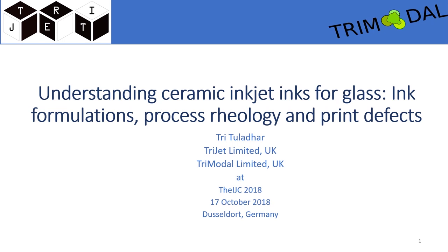that. That's a part, but I'm looking at ceramic inks printing on glass, which has ceramic inks plus a glass frit, so it's a two-particle system, which is much more complex than your tile. And more important, we're printing on glass, right? So there are so many defects you don't see printing on tiles. They come when you're printing on a hard substrate. Like the former speaker talked about printing on the edges and all that, the line definition becomes quite a critical issue, which you don't see when you're printing on a soft substrate.